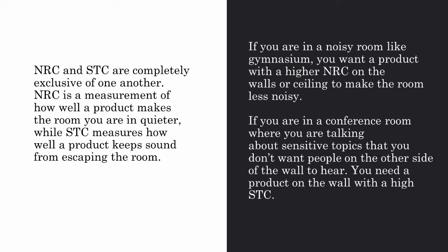NRC is a measurement of how well a product makes the room you are in quieter, while STC measures how well a product keeps sound from escaping the room. If you are in a noisy room like a gymnasium, you want a product with a higher NRC on the walls or ceiling to make the room less noisy. If you are in a conference room where you are talking about sensitive topics that you don't want people on the other side of the wall to hear, you need a product on the wall with a high STC.